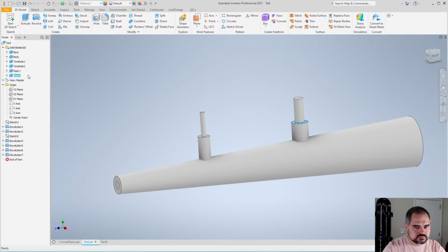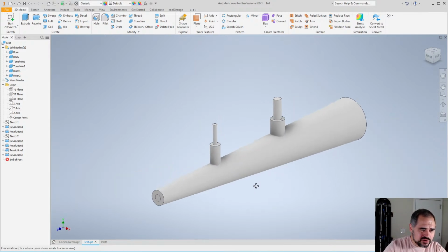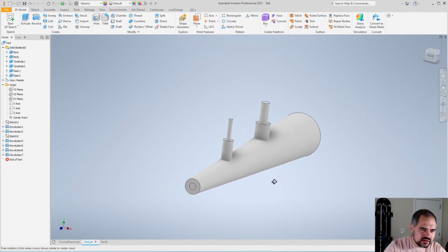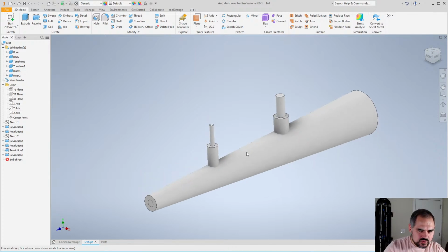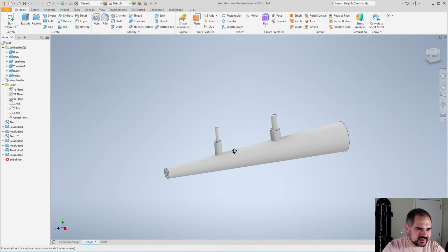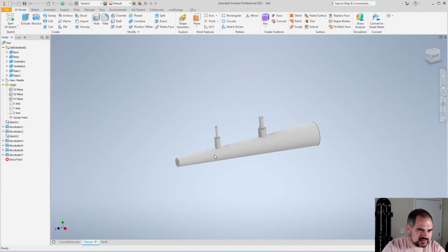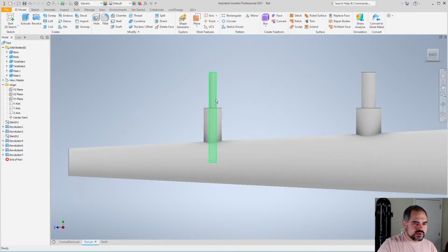riser 2. Okay, we're creating just a sample conical woodwind in Inventor, kind of just going over the method I used for maximum flexibility and general not breakingness. Okay, so we have our solids. The next thing we want to do is angle all 4 of these solids by the tone hole angle that we have defined.